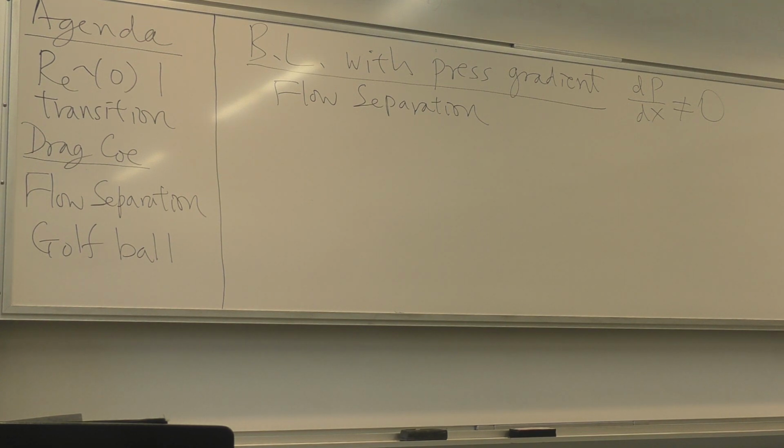On the turbine engine, similar phenomena can occur, where the flow can separate on the airfoil, except it's not a single airfoil, it's an array or cascade of airfoils around its circumference. And if one set, two or three blades, separate, then they influence the flow on the adjacent blade and can cause the entire engine to stall. If you go on YouTube, you have seen some pictures where the flame, the fire, is coming out from the combustor of the engine to the front of the engine. Very spectacular. But you don't want to be on that commercial airplane when it happens. And it happened before, on the 747.